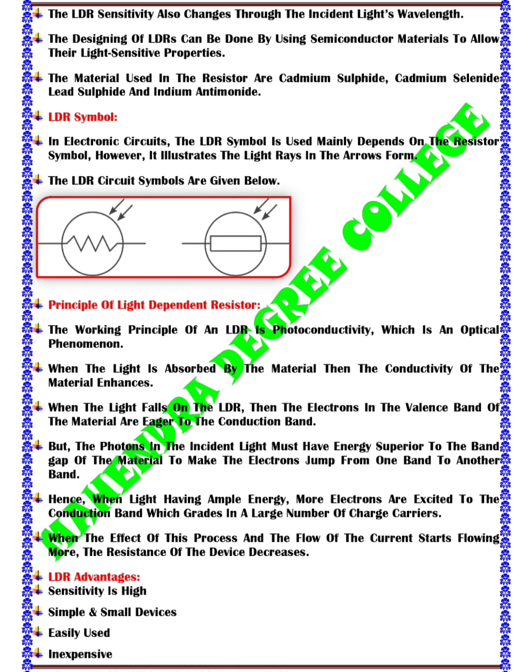Next, the topic of photoresistor will be continued. The sensitivity of a light-dependent resistor (LDR) changes with the wavelength of the incident light. LDRs are nonlinear devices, meaning their sensitivity varies depending on the wavelength of the light falling on them. Different LDR materials have different spectral response curves, meaning they are more or less sensitive to different wavelengths of light.